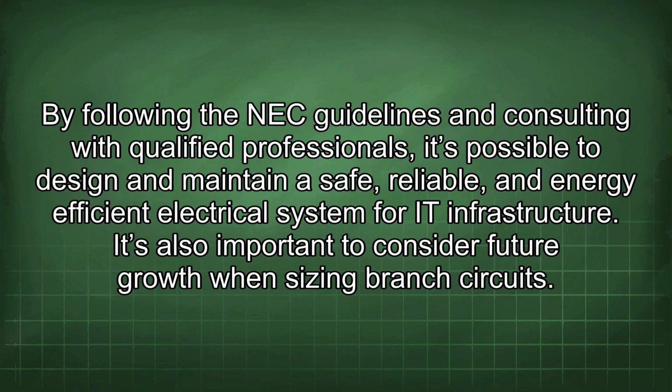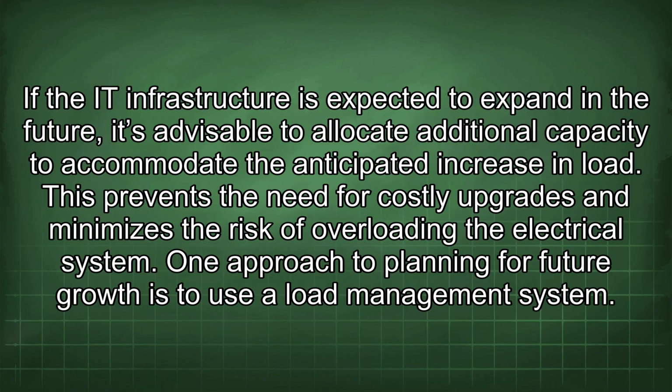It's also important to consider future growth when sizing branch circuits. If the IT infrastructure is expected to expand in the future, it's advisable to allocate additional capacity to accommodate the anticipated increase in load. This prevents the need for costly upgrades and minimizes the risk of overloading the electrical system.